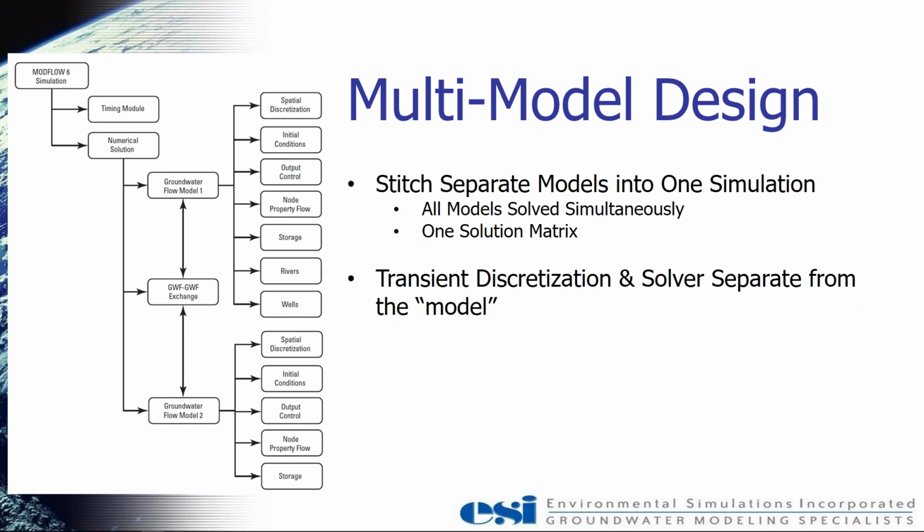This is something that Groundwater Vistas has never really adopted, mainly because I think MODFLOW USG does it much better by just embedding models together using nested grids and so forth. However, the multi-model design in MODFLOW6 is even better than LGR because it creates one matrix and solves